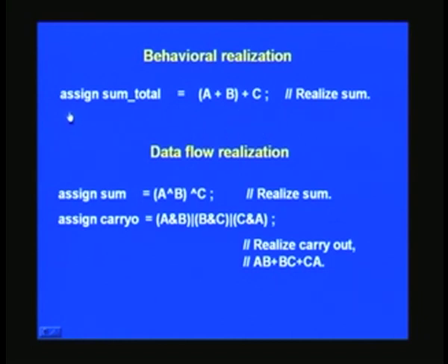And you will notice that in a single line we can realize a full adder. And another beauty of this is that it works irrespective of the bit precision. Suppose you want 16-bit precision for A and B, you can still use the very same statement. The only thing is you will have to declare A, B to be of that precision on the top of a program, which we will be covering later on.